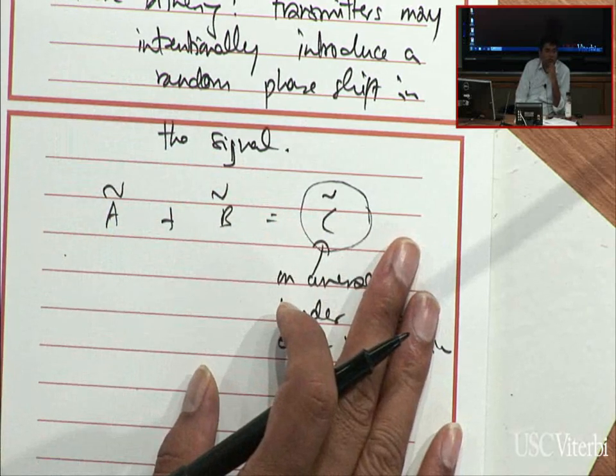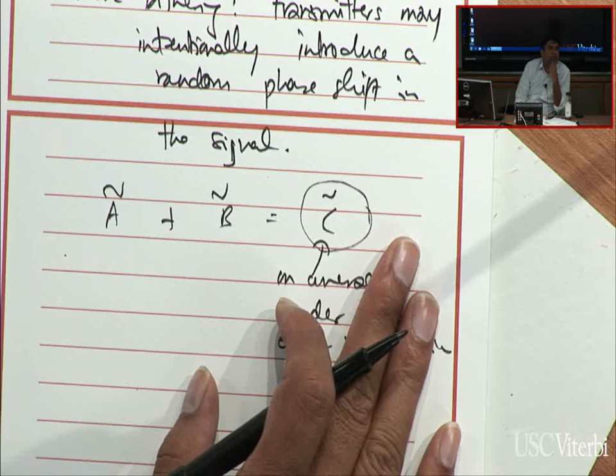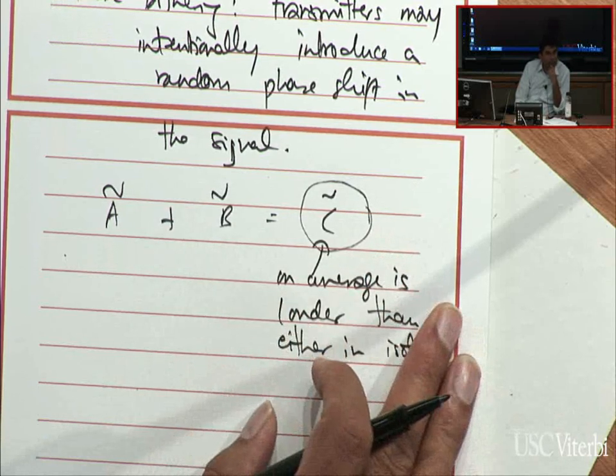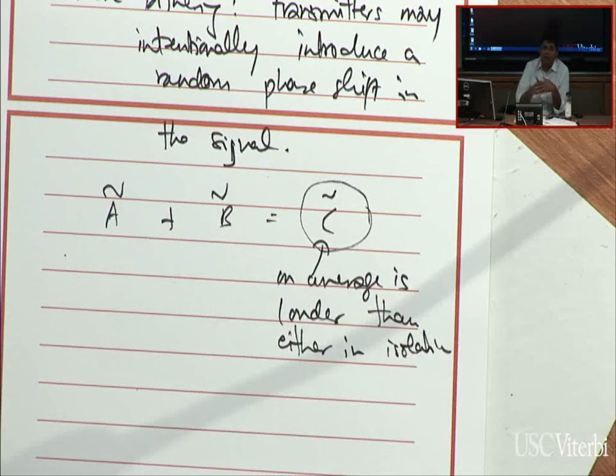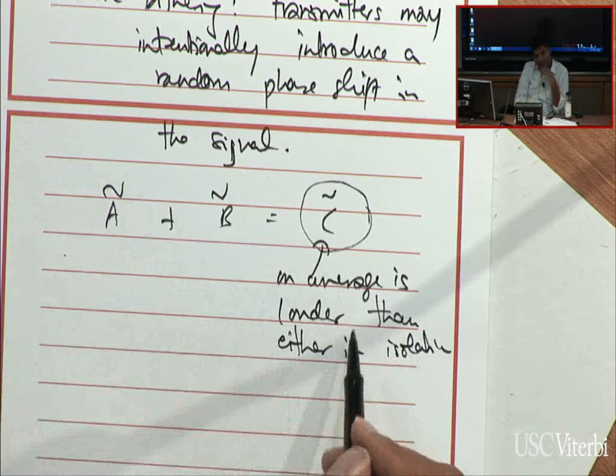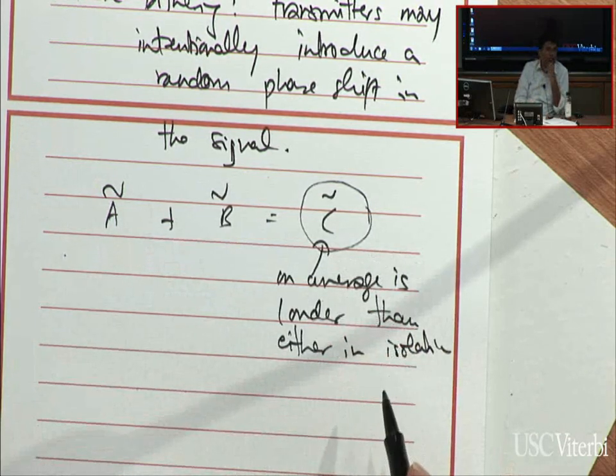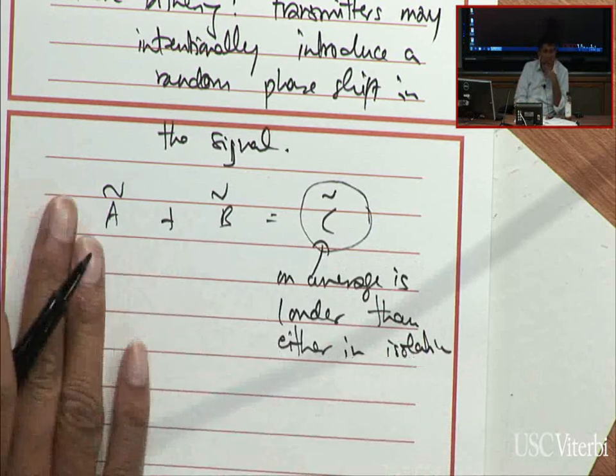And one way to convince yourself of this is to do a simple Matlab simulation. You take two sinusoids and you add them up and you look at the amplitude of the resulting sinusoid. If the two sinusoids are perfectly in sync, of course, you'll get a much larger signal. If they're perfectly out of sync, you'll get nothing. But now you run a for loop, each time you put a random phase shift to the two sinusoids and you add up, and now you take the average signal strength you heard after doing this random phase dithering, what you'll find is that the average signal is actually going to be louder than if I just sent one of them.